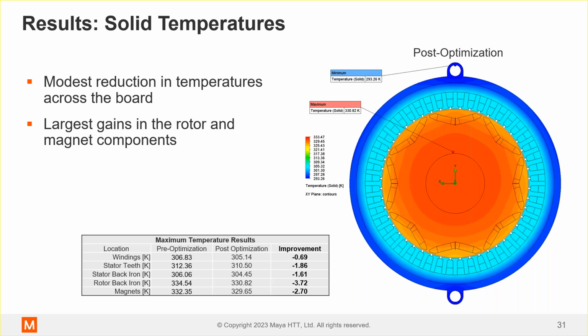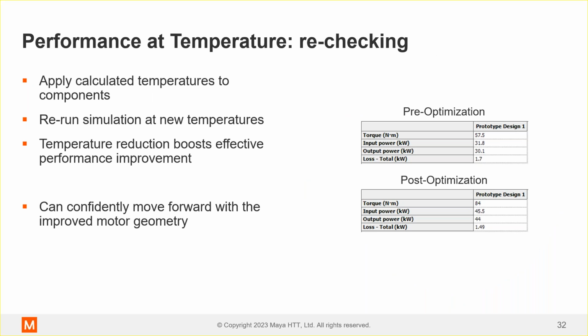consideration. And so what we did, to know how that improved our design in a realistic way, is we went back to MotorSolve and took our temperatures. David actually ran 2 solutions: he did a thermal simulation on the pre-optimization design, and then again on the post-optimization design. We took those temperatures component by component and put them back into MotorSolve, where it could run the electromagnetic simulation again, using those new temperatures on the components instead of just the default room temperature that we used initially.